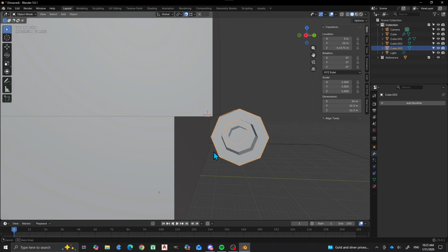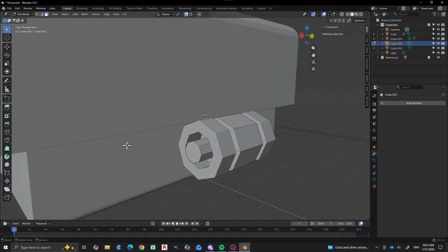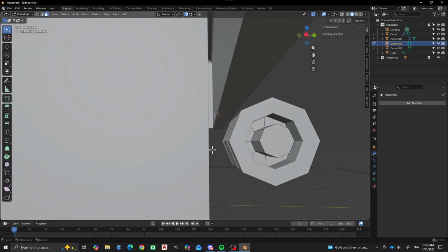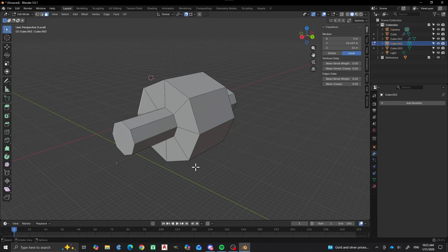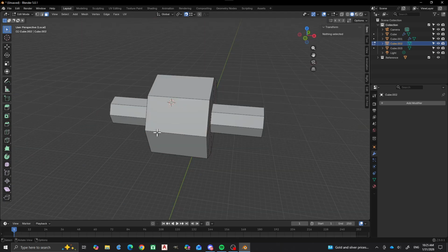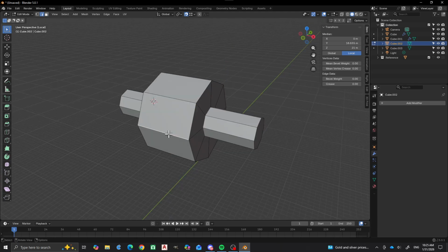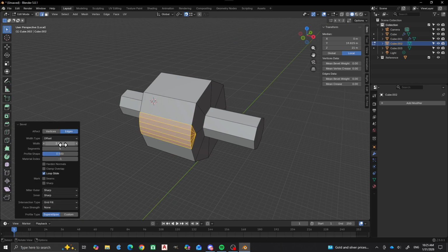So what I want to do is I want to connect this one to this box piece right here, okay? So now what we can do, so we can say, all right, well, now I want to have this piece, this edge right here. And I can say Control B. And I want to have that at a bevel of 3. And I want that just at 0 segments.